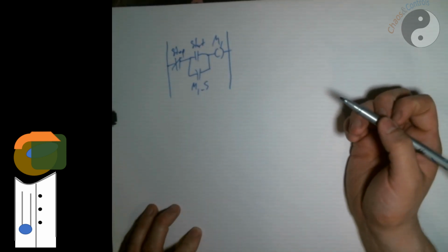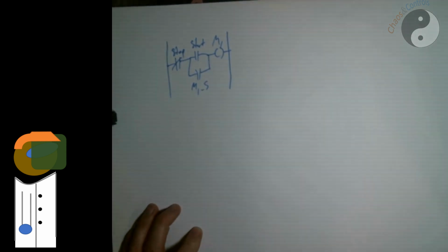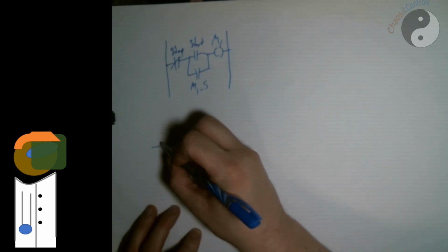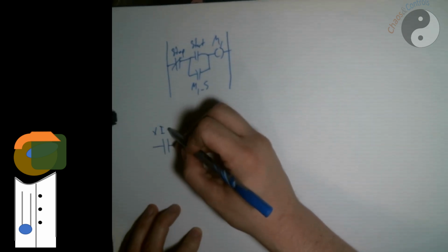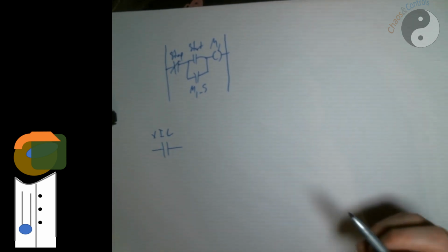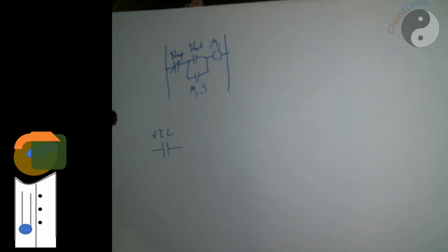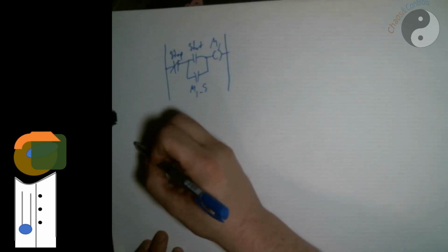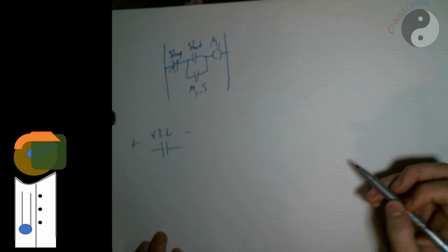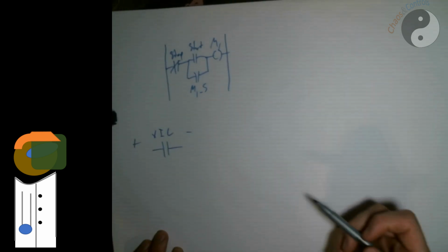The most quintessential, the most fundamental, the most common logic element that you will ever find in ladder logic is this symbol here, sometimes denoted as an XIC. I think I got that right. In other words, examine if closed. And so an examine if closed basically says that we are going to allow power to flow from this side to this side if this signal is closed.